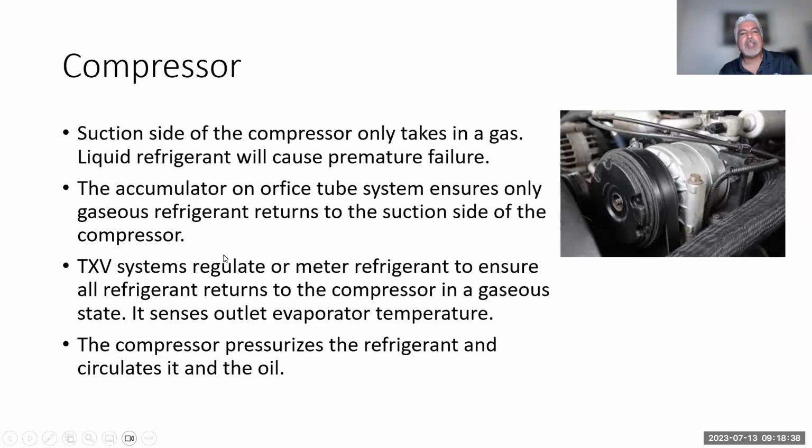Now, like we were talking about the compressor, the suction side of the compressor only takes in a gas, like we said already. Hopefully you can understand that. So that means all that refrigerant must be boiled in the evaporator. So what if it's a cold day? How do I know that the refrigeration system is not going to send any liquid? Maybe it didn't boil at all.